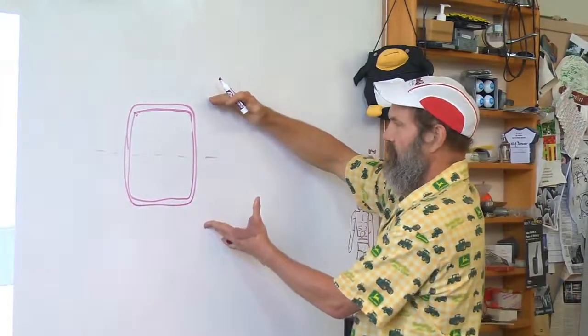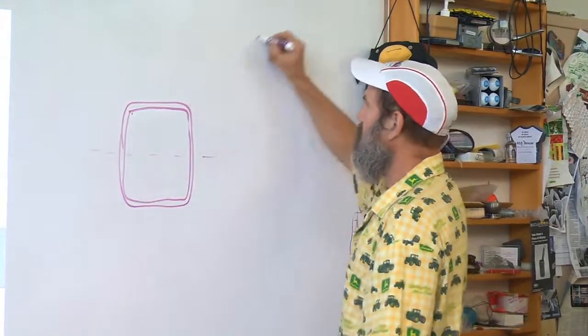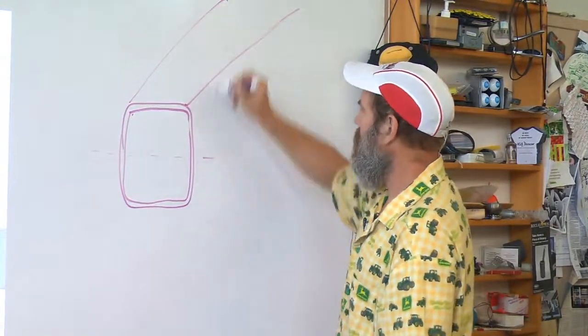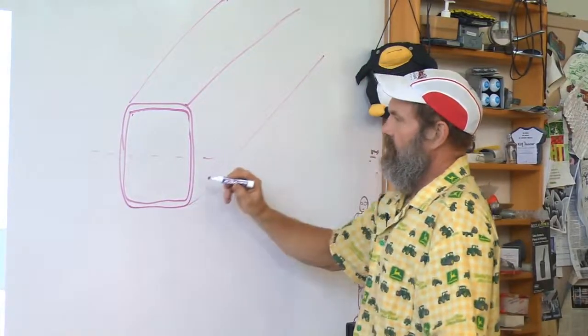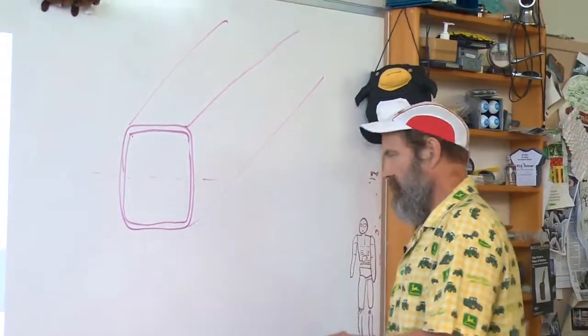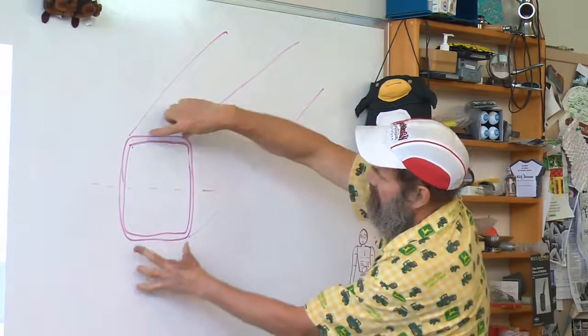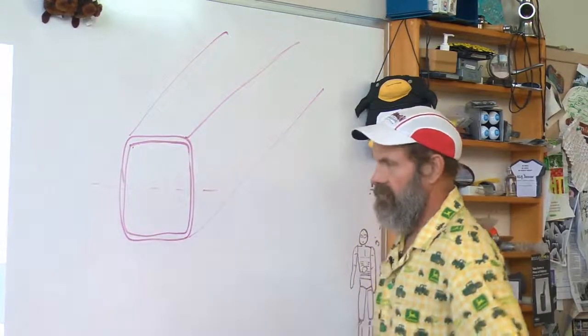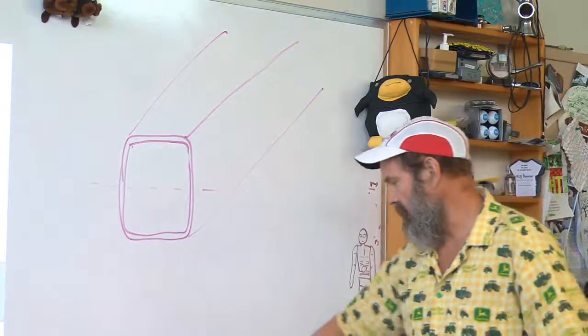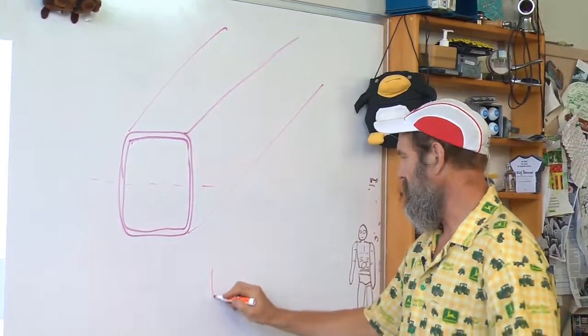So it's very stiff and strong globally. Here's my neutral axis, because I've put my area, my mass, far away from the neutral axis. Fantastic. Now I've designed this machine, for example, a bridge-type machine.